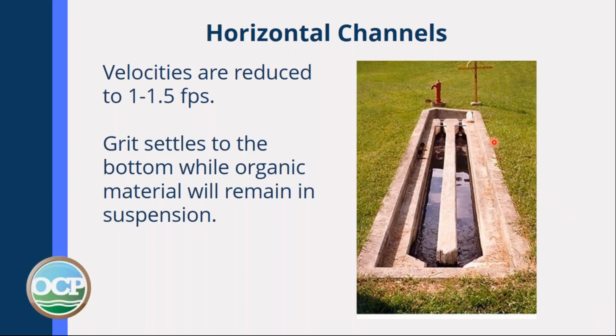As water flows down this channel, things will settle out because the velocity will be lowered to maybe less than 1.5 feet per second. You don't want it much lower than that because nothing will get into your plant. The grit settles out and can be removed later. Everything else remains in suspension.